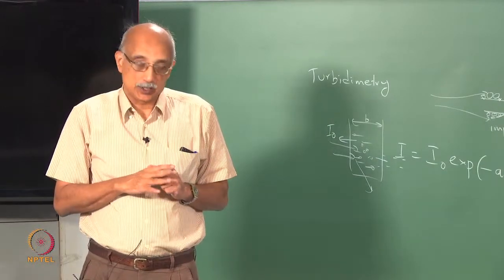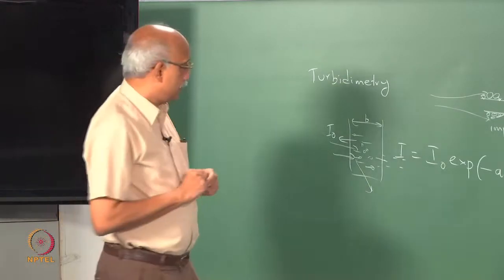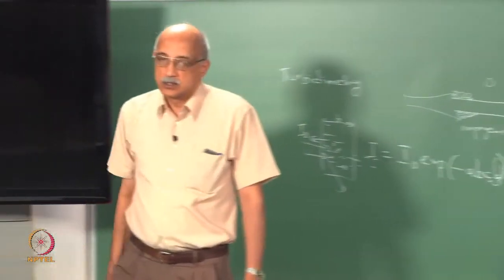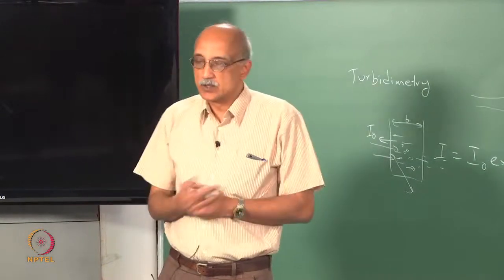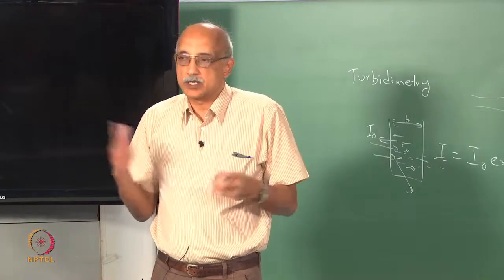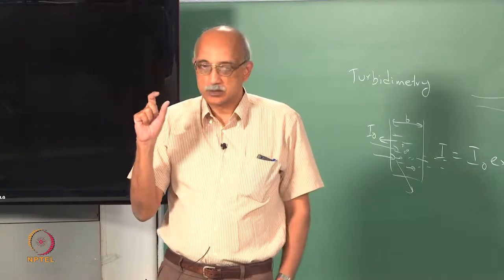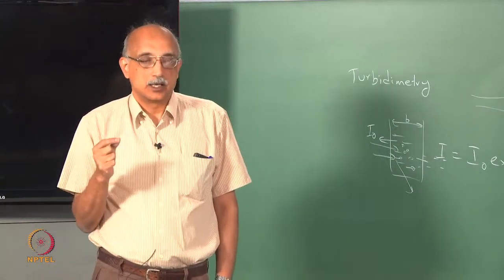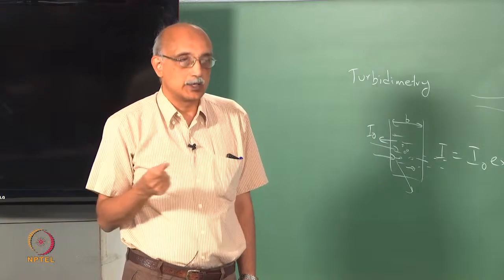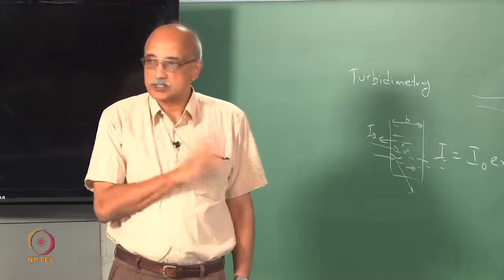Now, that is a useful measure certainly, but does it yield size? Size is obviously involved. If you can measure the scattering cross section, you can assume that that is related to the surface area. So, the total surface area of the particle is 4 pi dp squared, or pi dp squared. From that you can extract a mean size, and we talked about equivalent diameters in the last class. So, this will be a scattering equivalent diameter. So, you can at least get a mean size of the particles that are in suspension.